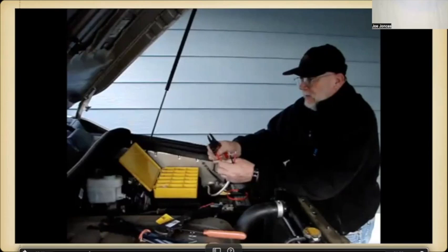It takes a fairly rough environment to do that. If you live out in the desert, you never have to worry about it. But living here on the coast, that's something that you got to make sure that you take care of. So if you're using untinned wire, be sure that you solder it as well as crimp it.